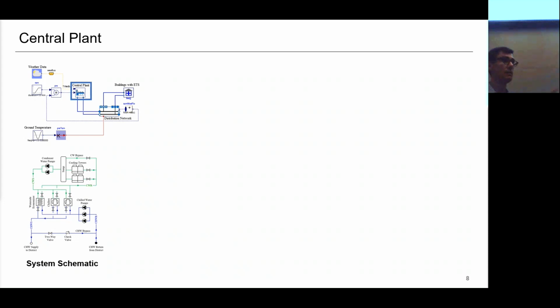And maybe just for clarity, we do have models now also where we can model the heat capacity of the water in the distribution pipes, which can be quite a considerable dynamic effect, in particular if you change the supply temperature. So those models are in the IBPSA library and in all the four libraries that depend on the IBPSA library.